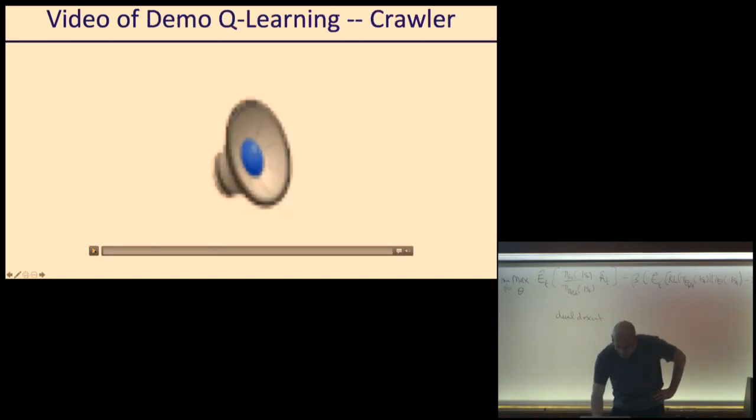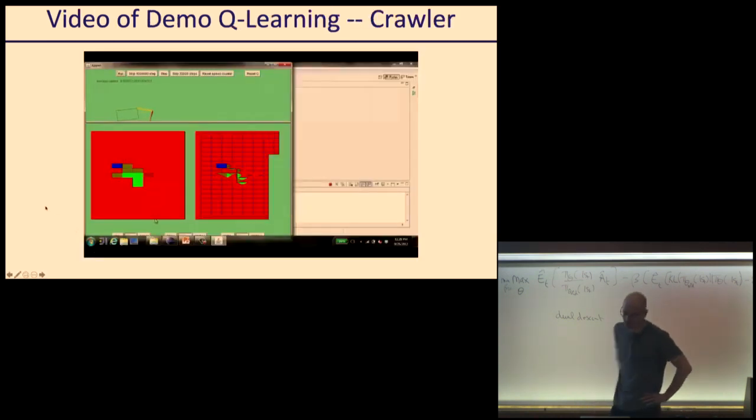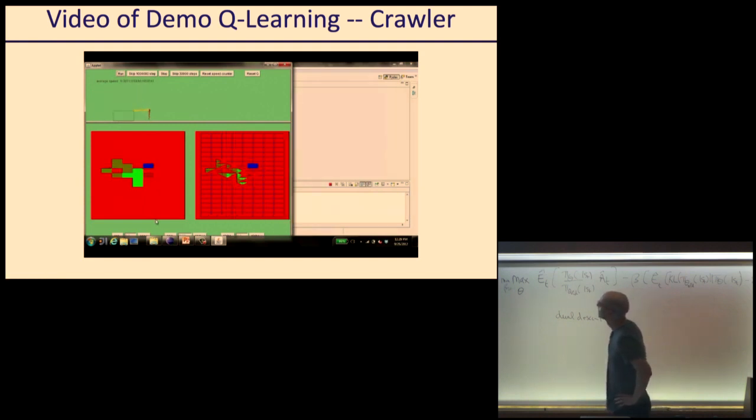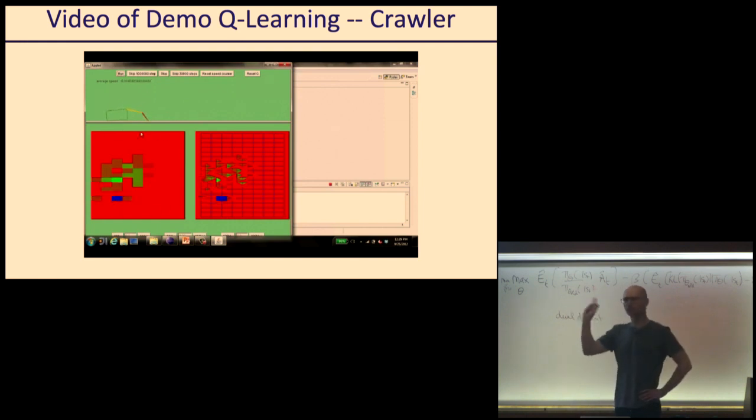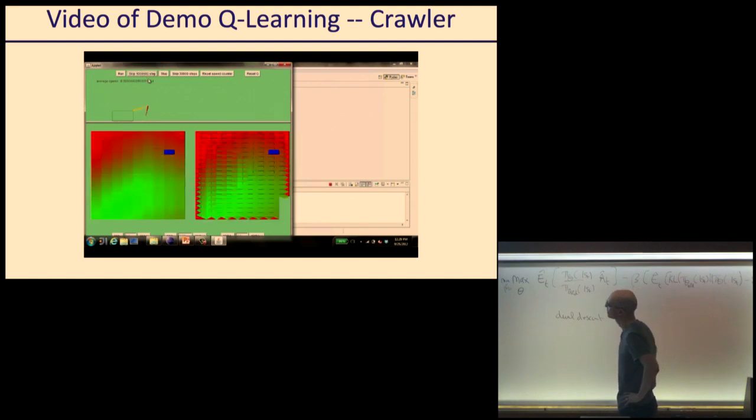Under the hood, we can also look at the Q values changing over time. On the left is the values. The horizontal axis and vertical axis correspond to the discretization of the 2 angles in that robot arm, the 2 joint angles. On the right subplot is the Q values, which relate to whether you increase or decrease a specific joint angle. We accelerated here, and we see that at some point we have some region with very good value and Q value, and other regions with very bad Q values and values, because that's where it's not in a good situation to move forward fast.